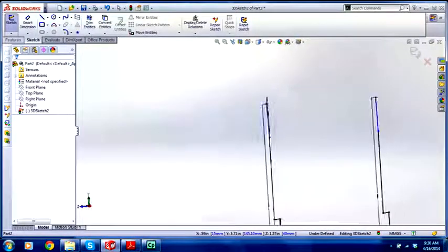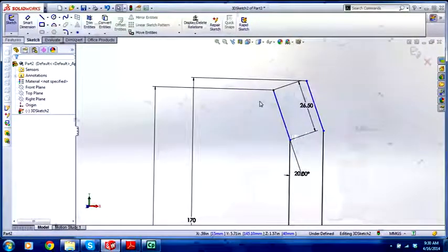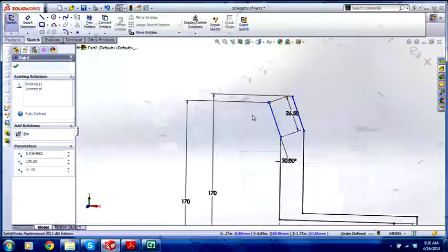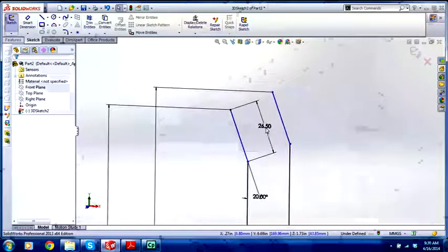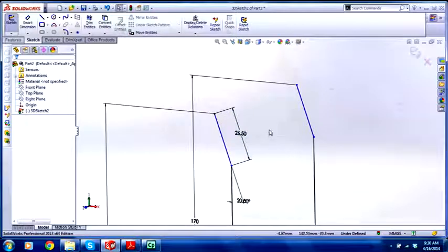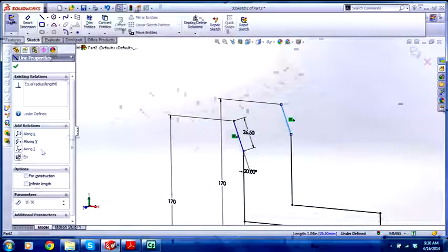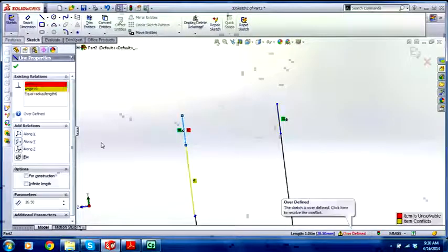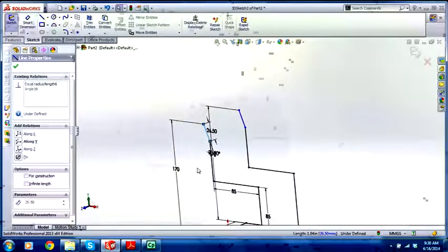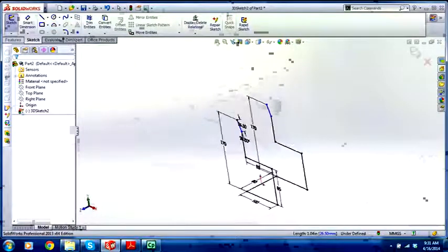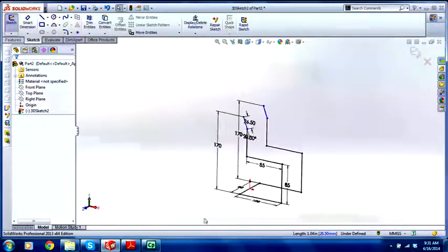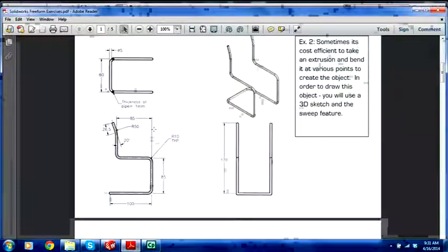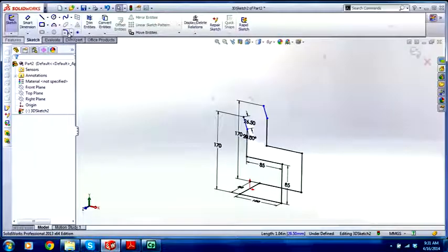How can I lock that in? And look, it's fine the way it is. I'd like this to be along the Y or along... No. Okay, well, let me get back to that for a sec. Bloody 3D sketches. And let's put some of these fillets in. Radius 10, typical. Okay, so what we'll do, we'll get a fillet of 10.